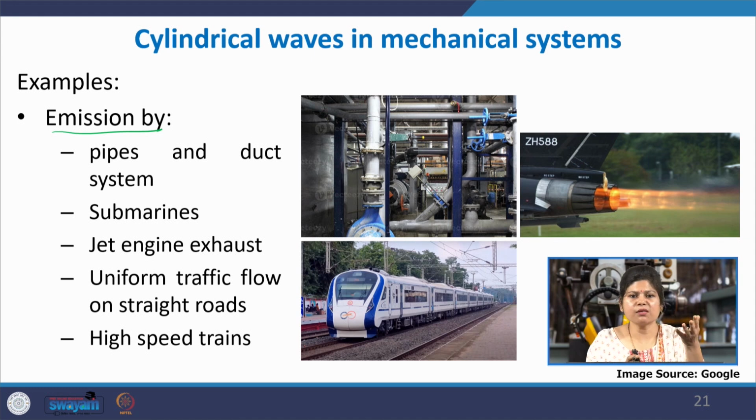When we were discussing harmonic plane waves, we saw that if inside the pipes we have some reciprocating motion that is generating sound waves, for example inside the tailpipe of a vehicle, where the piston of the engine is pushing the sound waves through the tailpipe, then inside the pipe it behaves like a harmonic plane wave, and as it emits outside into an infinite baffle or atmosphere, it becomes a point source. So, it emits a spherical wave. This is not that.